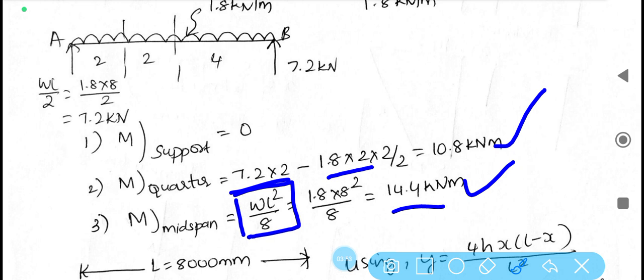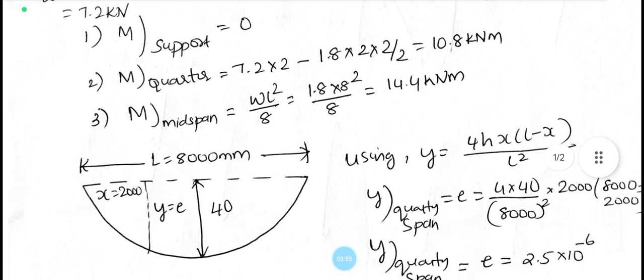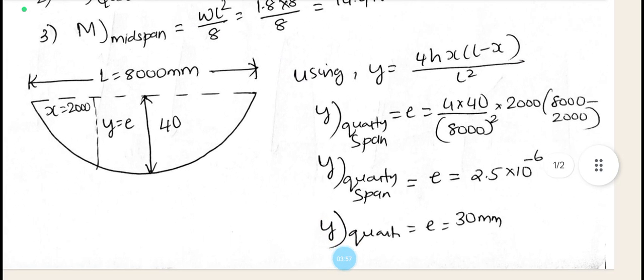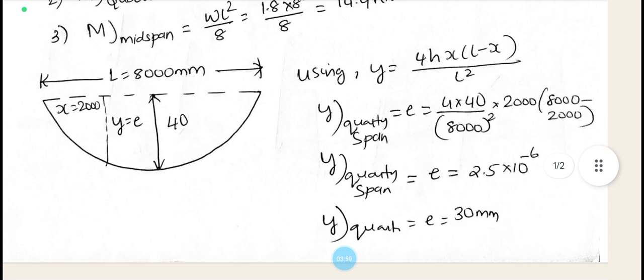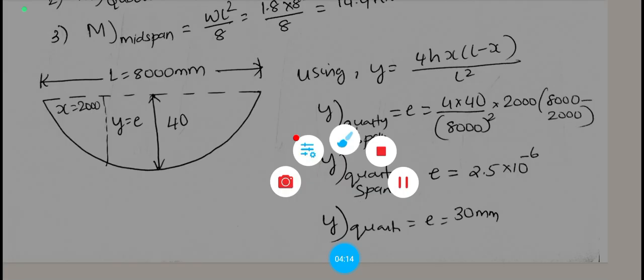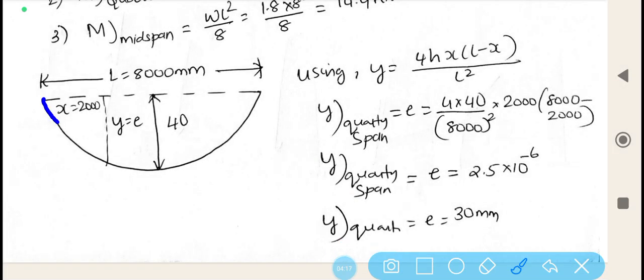And here one more important thing is that the given cable is a parabolic cable, which always has varying eccentricities. In the case of a straight cable, from start to end, eccentricity remains constant, whereas in the case of the parabolic cable, since it follows the profile of a parabola like this, eccentricity is not constant with respect to the neutral axis.